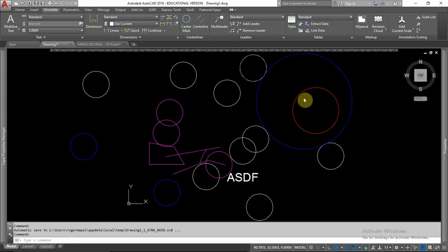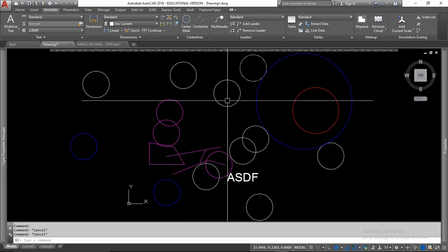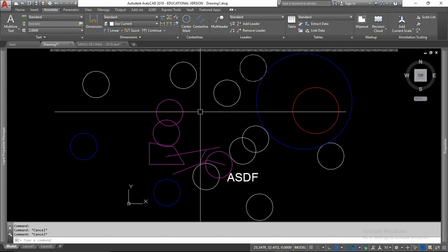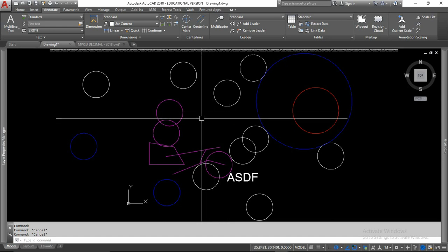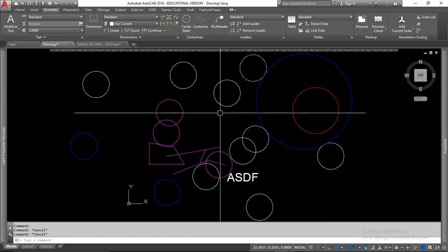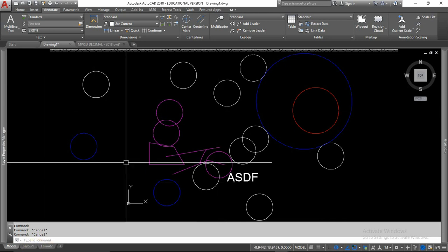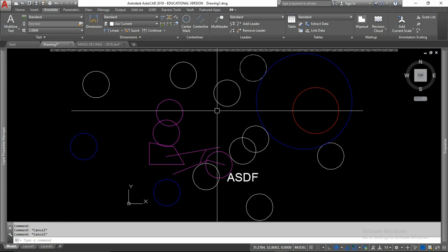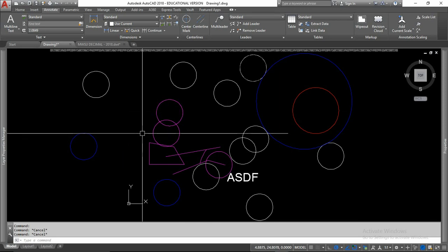What's going on here is the Model tab, model space, actually command alias MS, M space, which is what gets us to here. Model space, and what the other is called is paper space, or PS. They were very common and necessary prior to AutoCAD having layout tabs. The layout tabs, in my opinion, are much nicer, much easier, much clearer to deal with.